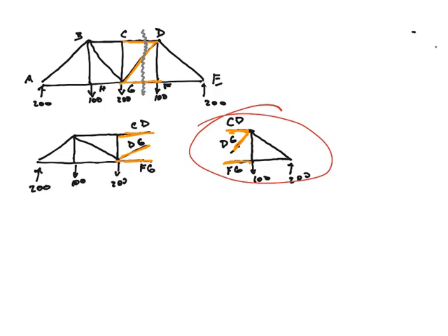But for more complicated problems, of course, one side of the truss may be way more complicated than another side. Here, I'm going to use the right side because it's the easier side. Once you know which side to use, what do? Step 2, do global equilibrium again.